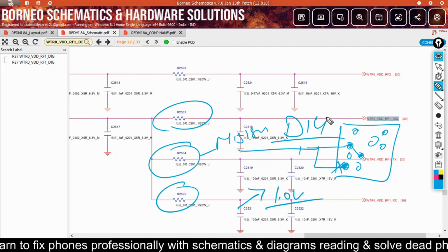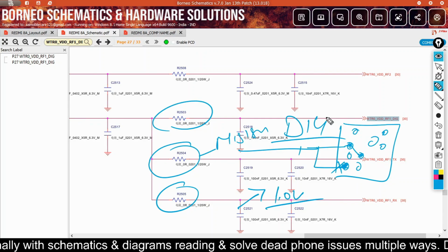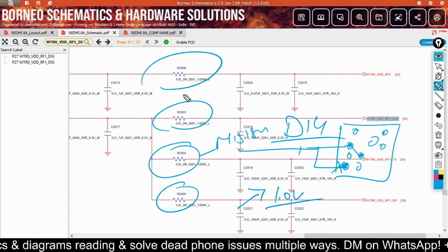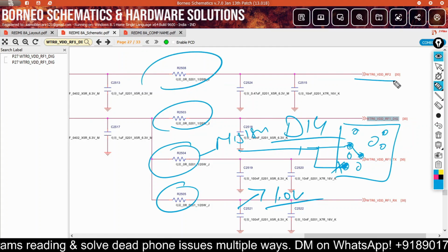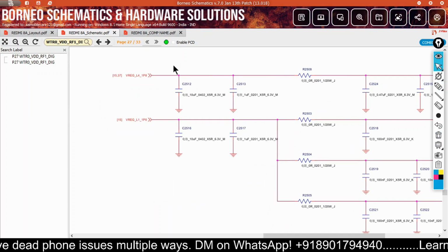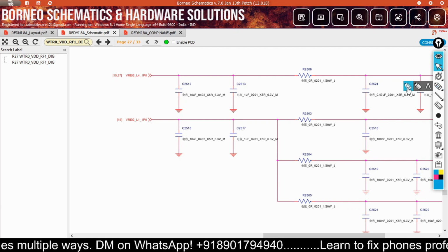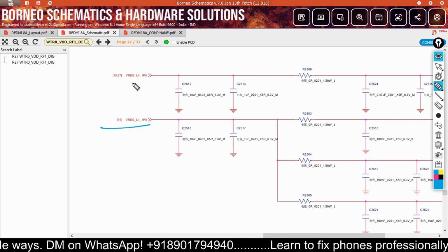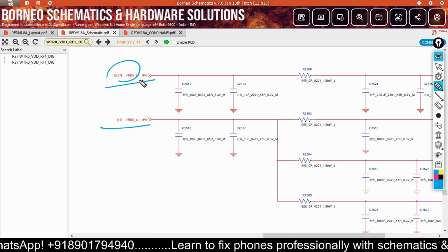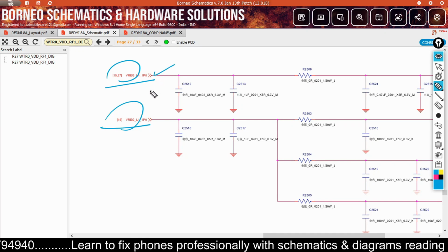Now this line comes from, I will tell you about this line later, more explanation, actually an advanced one, right? Now there is another voltage, another line, right? Now we see this line. First we clear this line. I hope you get it. There is an L4. Now this is a 1.8 line. As I show you, there are two voltages, right? 1.0 and 1.8. Now this one comes from the L4 LDO, and this one comes from the L1 LDO, right?